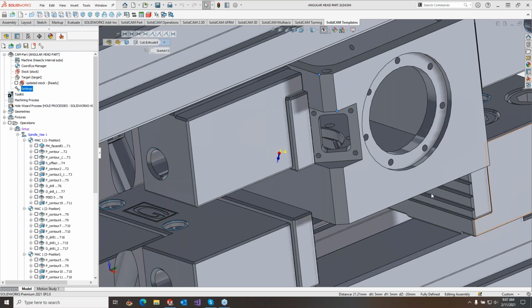You can even go into SolidCAM and delete the tools and the operations that are active in the simulation, and the simulation doesn't affect it. It's completely like its own isolated application toolkit type of thing. When you launch a simulation, all the data is prepared, all the things given to it, and there is no more communicating back to SolidCAM for anything. No toolpath links, no tool information, nothing.